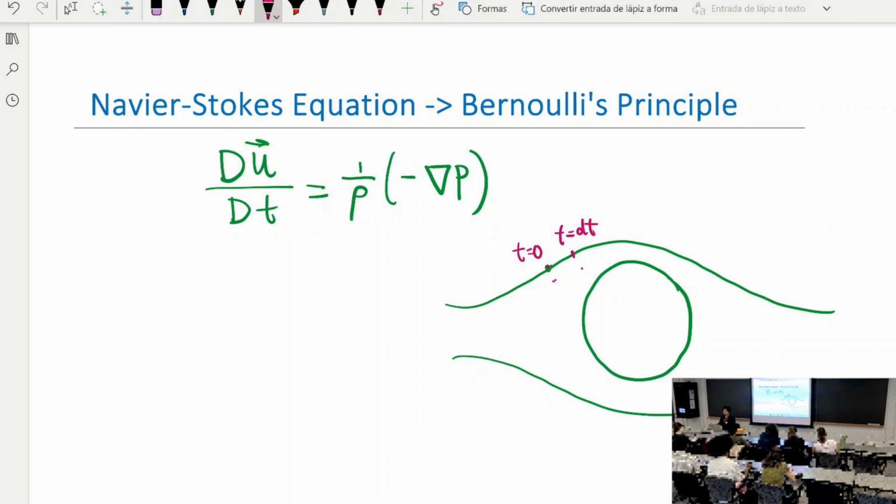The pressure is also going to be constant. Okay, so let's actually look at this small segment. We know the velocity here is u, right? Which means over a small distance, the flow particle has traveled a length of vector u times dt, right? Let me denote this small length as dl equal to u times dt.